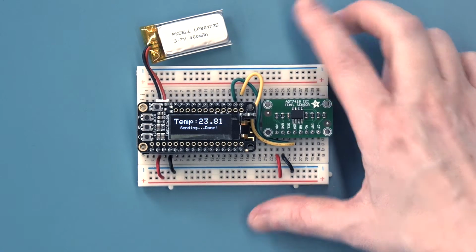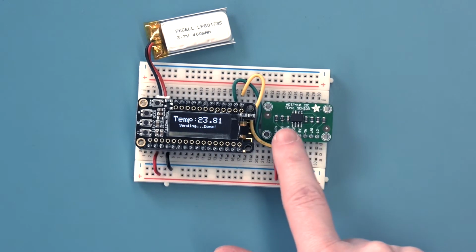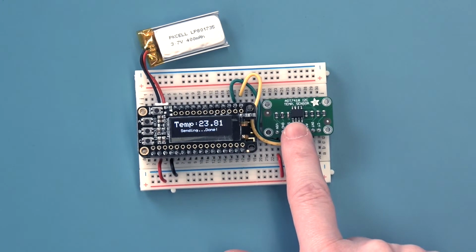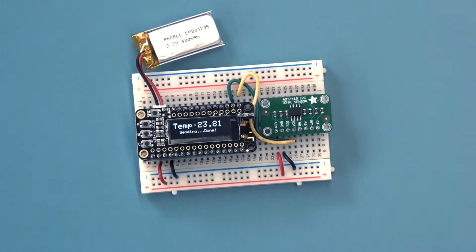Likewise, here's an example using the ESP8266 Feather with an OLED on top and an Analog Devices ADT7410 wired up on a breadboard. With the ESP Feather, we're stuck with a microcontroller rather than a full computer, so we don't use Python. Instead, we'll stick to Arduino C++. The trade-off is we have much lower power usage, so we can run it off a battery, and faster boot. But we also have to be more careful with memory and link management.